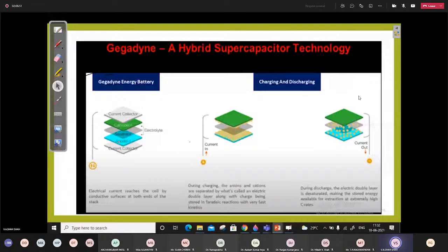So load terminal voltage can be kept almost constant with respect to the vehicle driving conditions. So these are the advantages we are getting by putting a DC to DC converter in this energy storage device to design a hybrid power source for EV. Again, it will regulate the power flow from input to output. The weight of the power source for a given peak power can be smaller than that of the passive power source for the same load. This is another advantage we are getting.